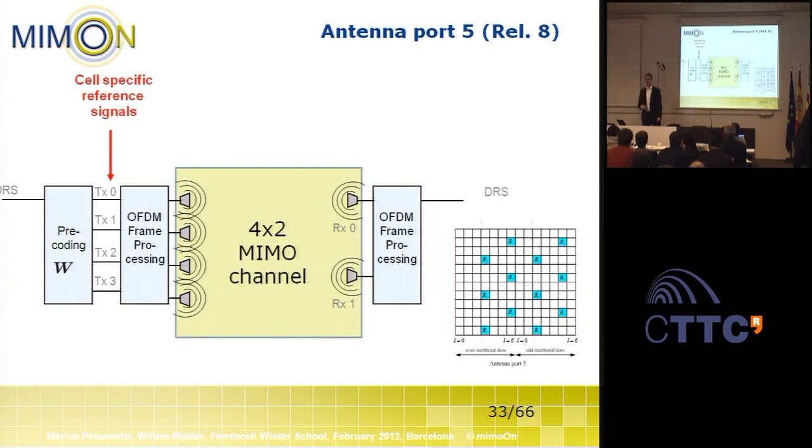This is done using user-specific reference signals. On top of the cell-specific reference signals that each user is receiving to estimate the MIMO channel, we now have some specific reference signals, as illustrated here in the time frequency domain.